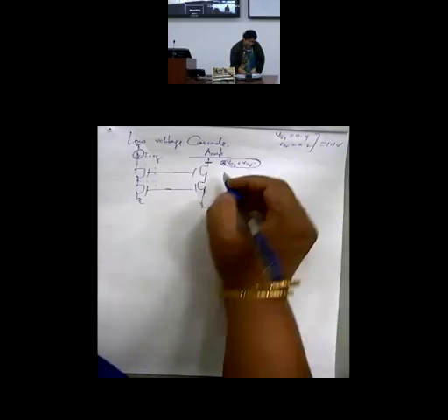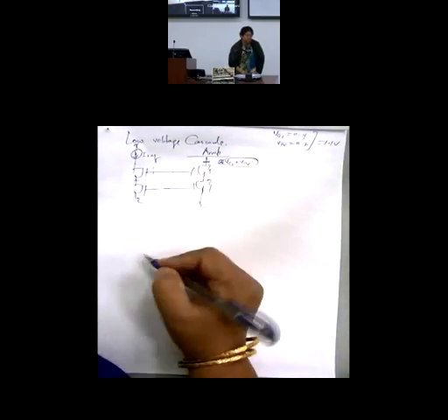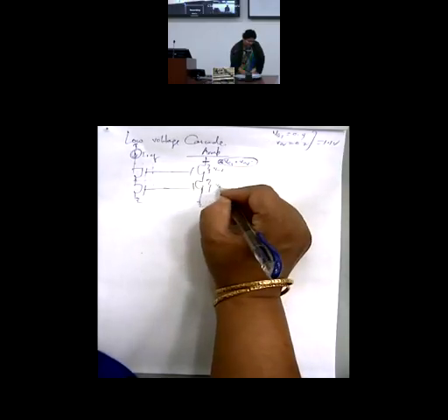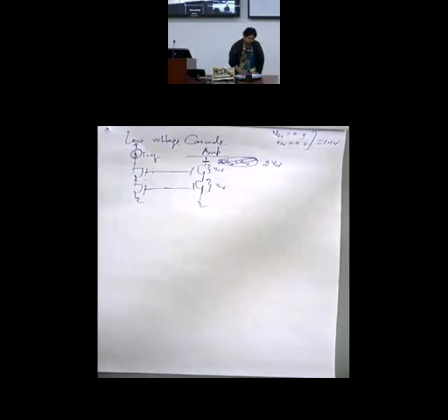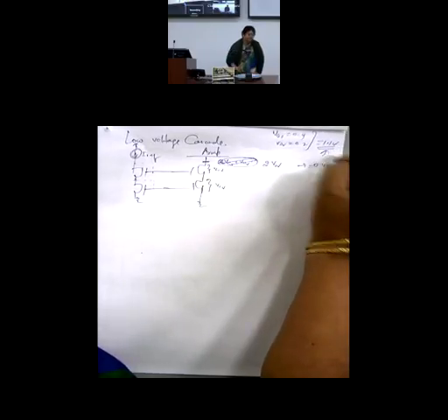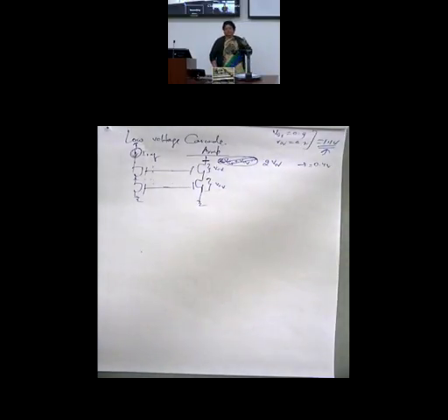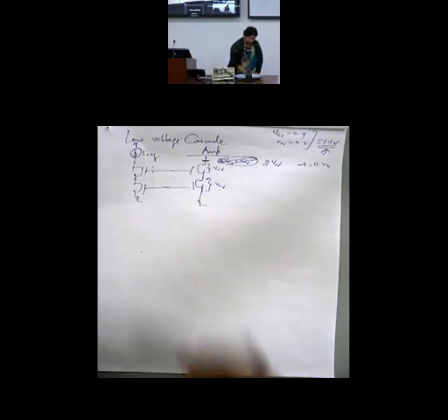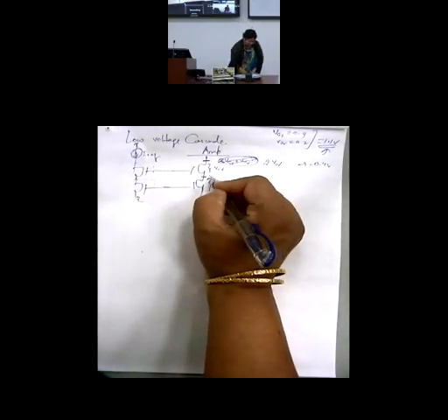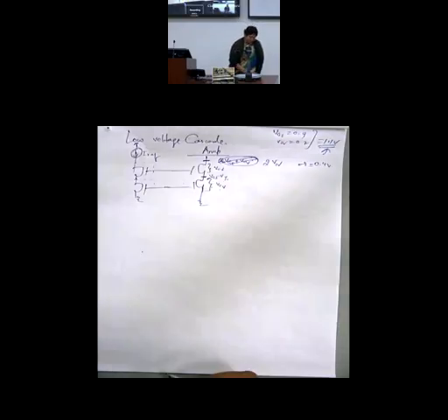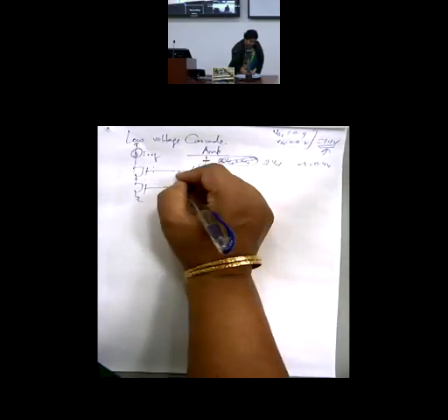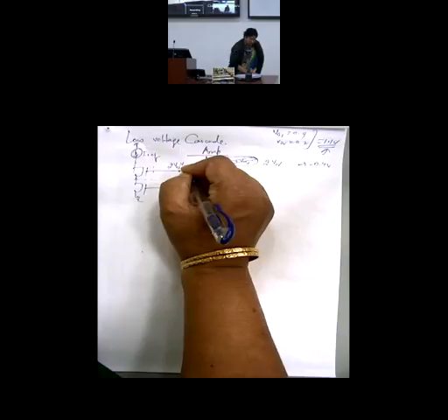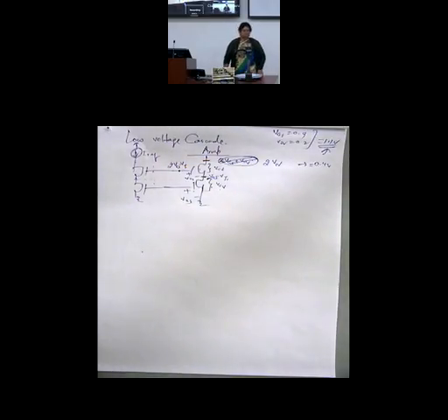So I want minimum, I say this is to be saturation, this is to be saturation. So 1 V overdrive here, 1 V overdrive here. I can easily bring both of them in saturation only by using 2 V overdrive. That means a total voltage loss of only 0.4. So why should I go for 1.1? So I do a back calculation. For this to be V overdrive, this comes at VGS minus VT. This is VGS and this is VGS because they are matched. So this comes to 2 VGS minus VT or VGS plus V overdrive.